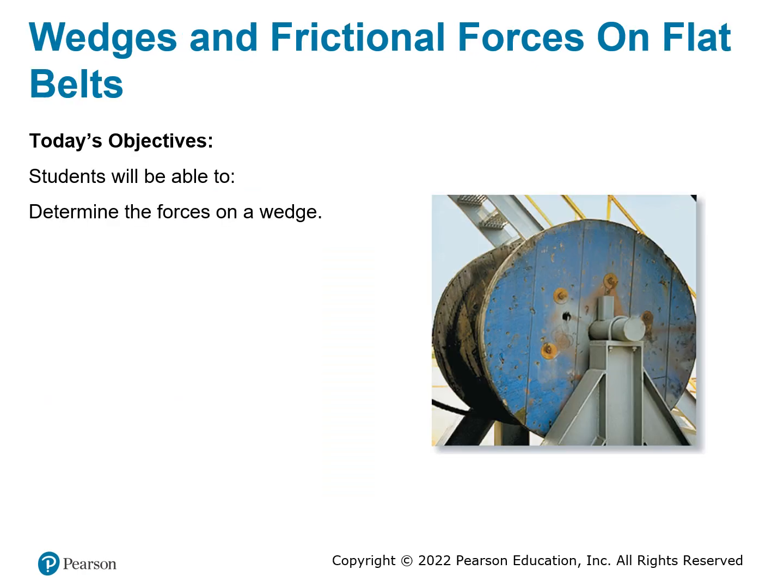So first, what is a wedge? Well, a wedge is usually used to apply a small force so we can lift a big weight. And sometimes you have a so-called self-locking system. If you use a wedge such as with this big wheel, and you have a wedge at the bottom, you can stop this big wheel from turning because of the friction between the wedge and the object that you are lifting.